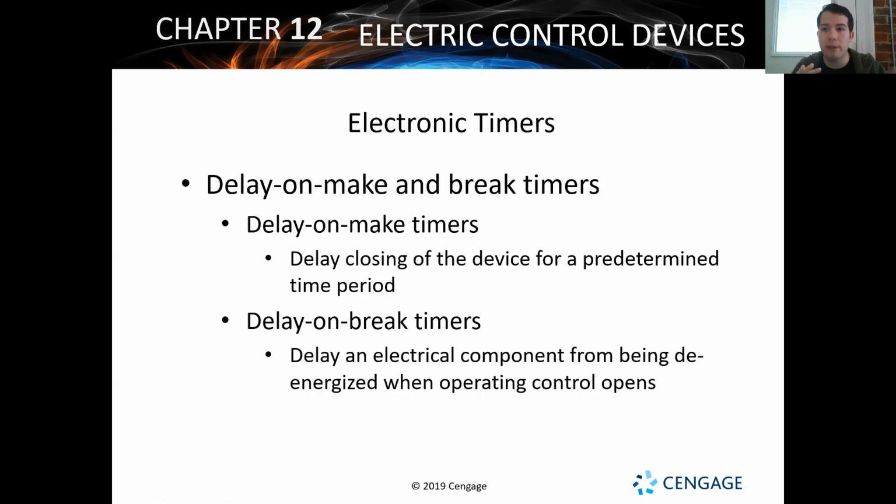For the newer ones, that's what it's going to be. Old school, it used to wait for the systems to get to a certain temperature. It would actually have a temperature sensor near your electric heat kit, near your heat exchanger to tell the blower fan, yes, the electric heat kit or the blower fan have cooled off enough, you can turn off the heat or turn off the fan motor. Nowadays, it's literally just a timer. And you can actually get individual controlled delay on break electric timers, or they're going to be integrated into a furnace control board or a fan control board or something like that.